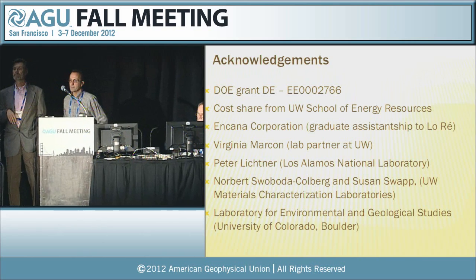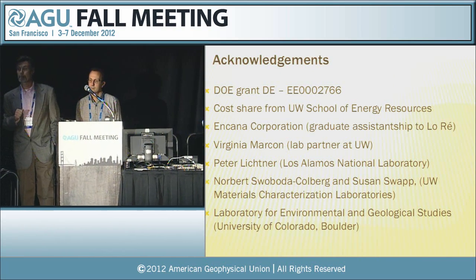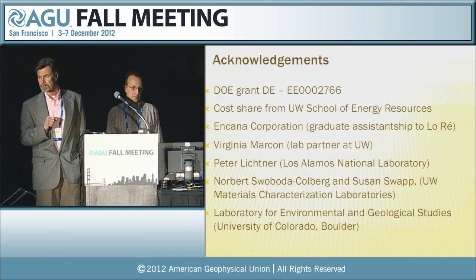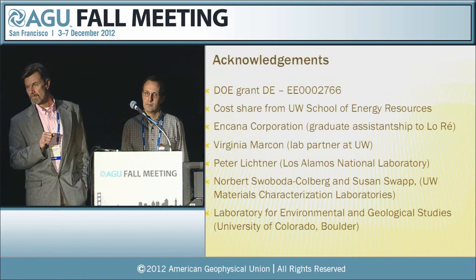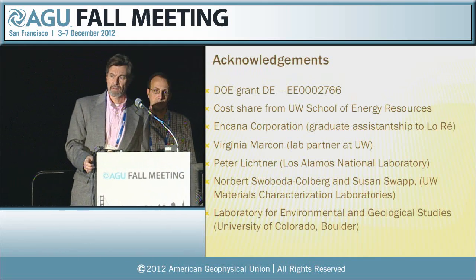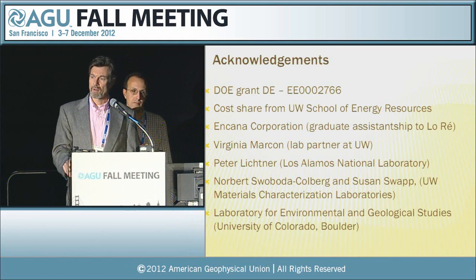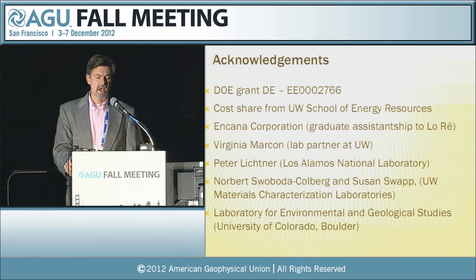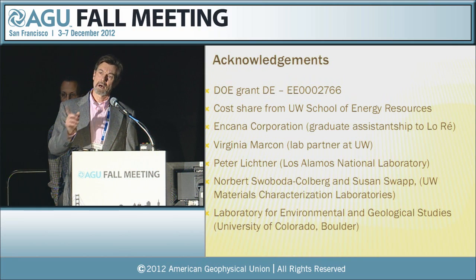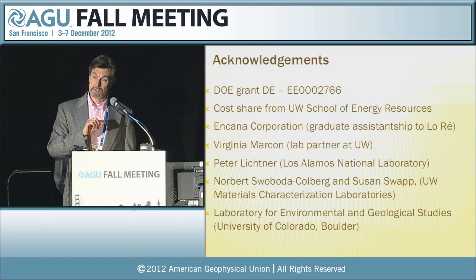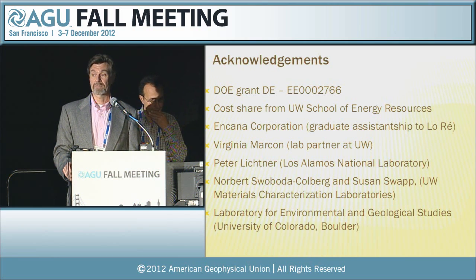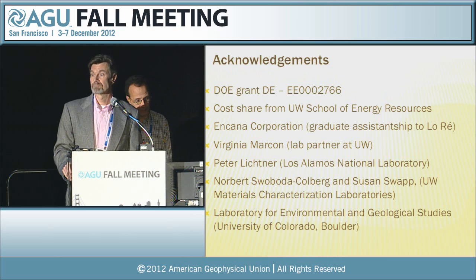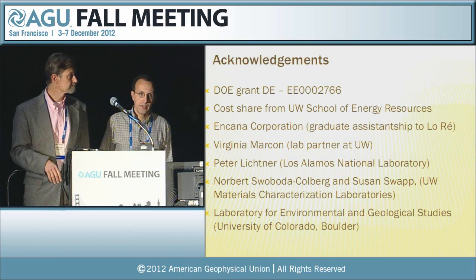Somewhat related to that question, you mentioned degassing promotes precipitation. Could you say something about the time scale of that precipitation? That's fairly instantaneous. It's pretty well known. You get degassing in well bores, in the oil and gas industry and geothermal, and calcite drops out pretty rapidly. On the time scale of these experiments, it's hours. You can make very beautiful calcite crystals within hours. Thank you.